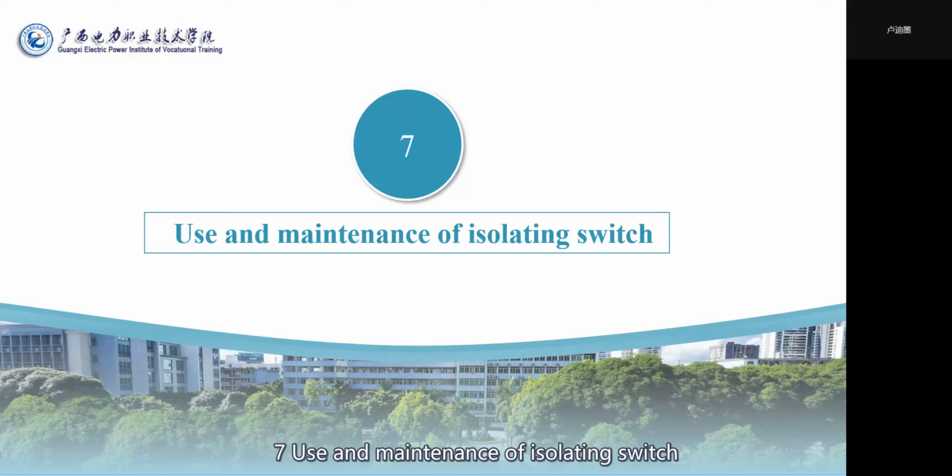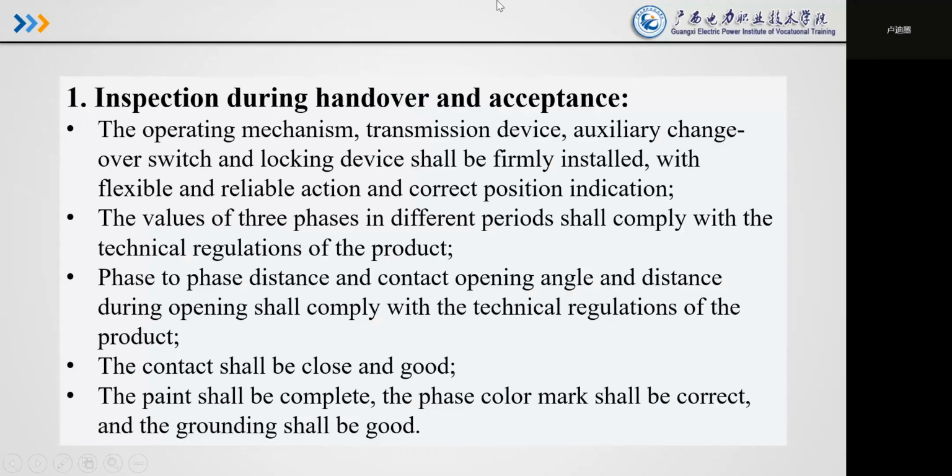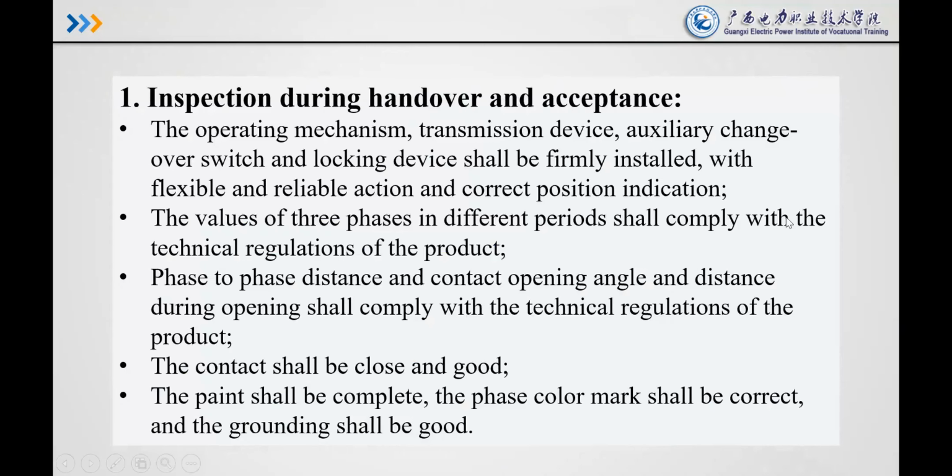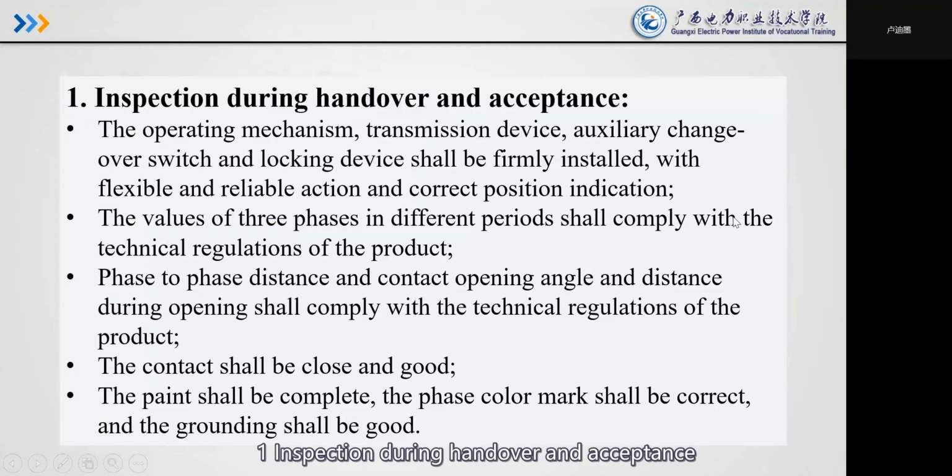7. Use and maintenance of isolating switch. 1. Inspection during handover and acceptance. The operating mechanism, transmission device, changeover switch and the lock device should be firmly installed, with flexible and reliable action and correct position indication.